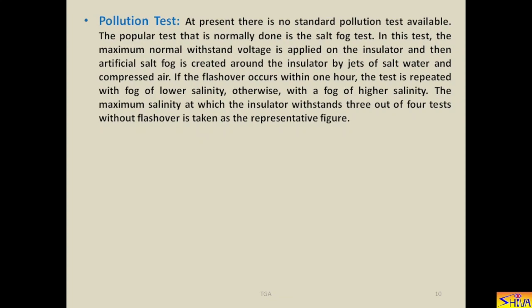Then it is pollution test. At present, there is no standard pollution test available. The popular test that is normally done is the salt fog test. In this test, the maximum normal withstand voltage is applied on the insulator, and then artificial salt fog is created around the insulator by jets of salt water and compressed air. If the flashover occurs within 1 hour, the test is repeated with fog of lower salinity, otherwise with a fog of higher salinity. The maximum salinity at which the insulator withstands 3 out of 4 tests without flashover is taken